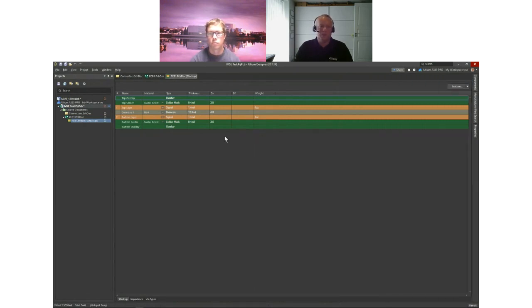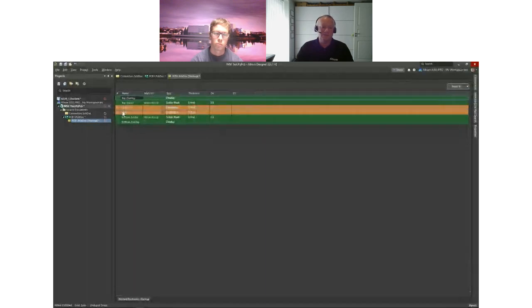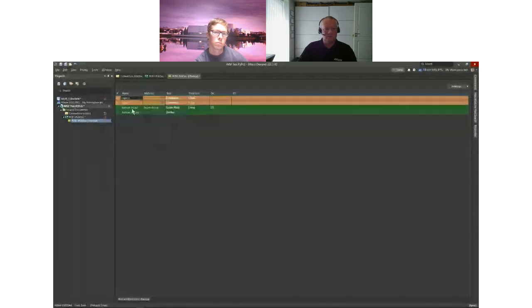So here we go. You can see I have the top overlay, I have the solder resist, I have my copper layer, I have the dielectric FR4 core here, and so on and so forth. So let's enable the printed electronics here. By doing so, I will also delete the core because it's not needed anymore. However, since this is going to be injection molded into some project, I will also remove the top overlay and the top solder here. So let's delete those layers here. Delete layers and delete these layers also. So now I'm basically down to 2 copper layers.